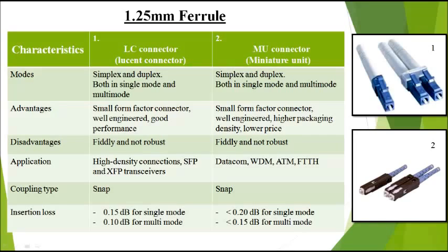LC connector has been widely used in high density connection, SFP and XFP transceivers. LC connector uses snap type of coupling, 0.15 decibel for single mode and 0.10 decibel for multi-mode are the insertion loss for the LC connector. The second one, the MU connector.